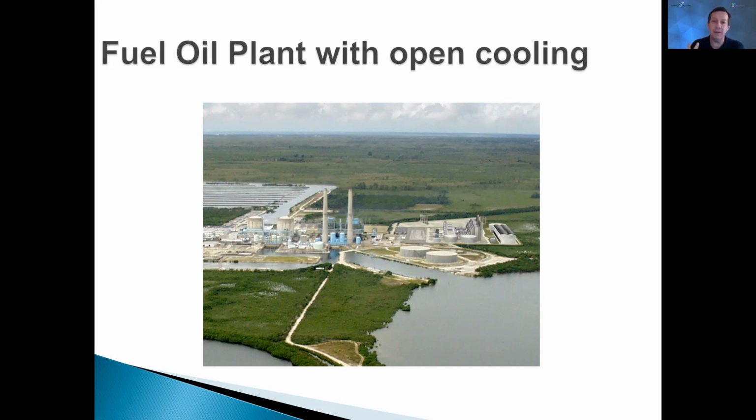You could see here that if they are using the lagoon for cooling water and you have a heat exchanger leak, the water would go from the lagoon into the heat exchanger where the leak is occurring, and then go right back out into the lagoon, contaminating the environment. In the catchment basin in the back, it will still contaminate that. It's obviously owned by the plant, but they don't want to contaminate that. It's open to the environment.